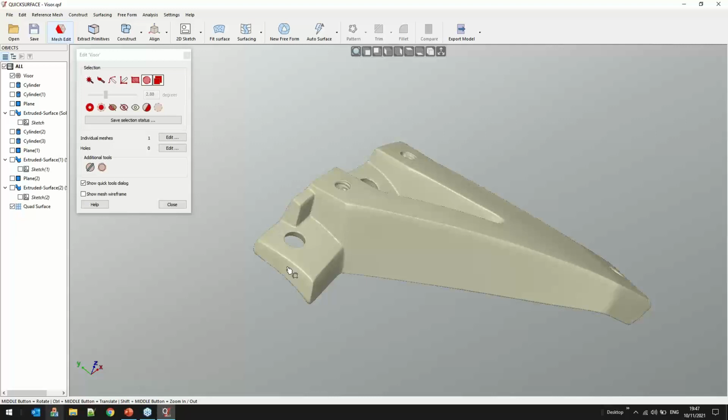Let's take this cylinder here. I will just go and edit my mesh. We'll use the selection tools to get rid of this hole, which I would call defeaturing, just to remove the actual hole. We'll go and edit and close the hole. It's possible that sometimes you get problems from the algorithm like this one. So I'll just select this area and repair all of these small areas so you can get a nice and smooth result.